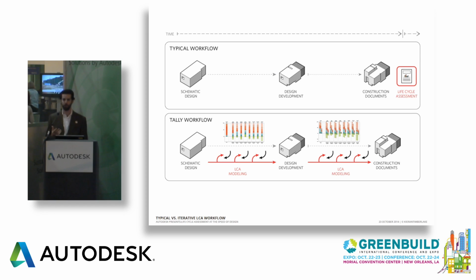And the solution that we felt was absolutely fundamentally necessary was iterative life cycle assessment, basically a life cycle assessment that was sufficiently easy to conduct that you could do it iteratively throughout the design process. So right at the beginning, you're in SD, you're able to do a life cycle assessment at that stage, and you can continue to refine it and run life cycle assessments on different scopes, whether it be discrete material assessments, design options, or whole building assessments, iteratively throughout the design process, so you can lead to a better eventual conclusion.